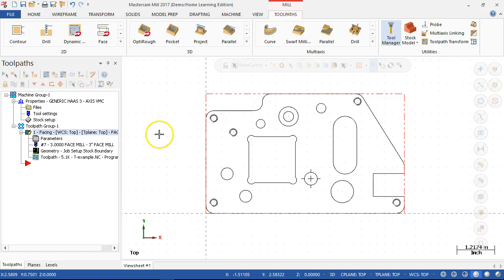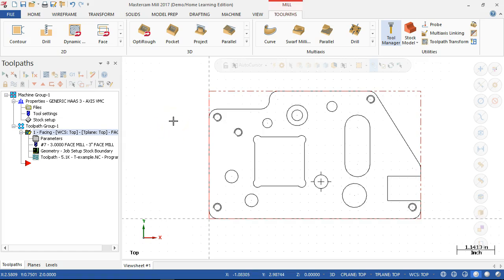All right, so initially I said we were going to stay with a 1/2 inch stock, put this on one of our little tooling plates, clamp it in a couple of positions, do all of the interior geometry, and then we would be able to change the clamps to the interior, run around the outside. All right, so that's a specific of the part. There's nothing that says that I have to go that way.